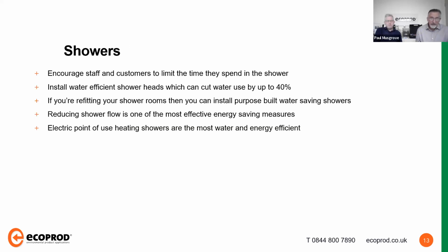Showers are no different. At the end of the day, we always use showers, and we can always try and encourage people to shower for less time. But again, one of the common things that we find, and in just two surveys I've carried out this week in the West Country, where they have a water scarcity issue already, the flow rates were in excess of 30 litres per minute per shower.